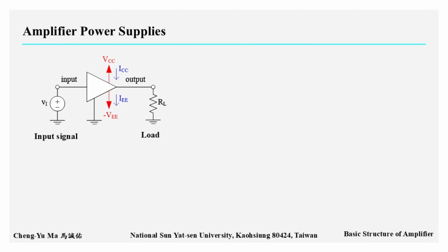In addition to signal input and signal output, the circuit itself must be supplied with a DC bias in order to start and operate. This is just like any electrical appliance. It must be plugged into a power source before it can turn on. Therefore, a circuit may have one or more DC bias sources. The slide shows an example using two DC bias sources, VCC and negative VEE. DC bias sources also generate DC currents, and these also contribute to the power when the circuit is operating.